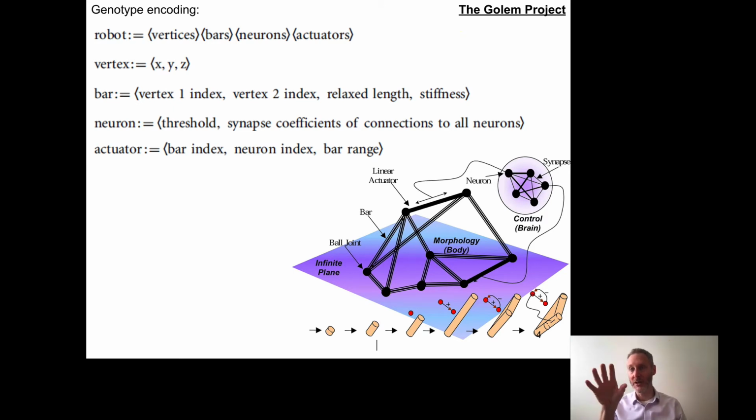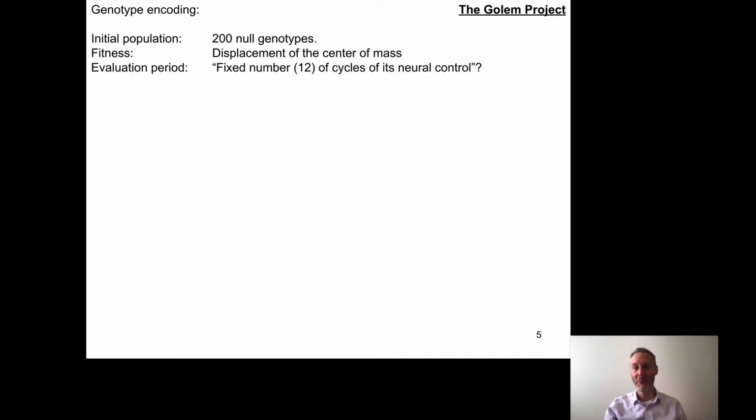Open loop control is we don't have that feedback loop through the sensors. The motors just send their value and the robot does its thing, but whatever the robot does does not affect the new values of the motor neurons. So this robot is actually controlled by open loop control. But how do we get this neural network going? What is sort of the input to this network that gets the motor neurons to start changing values?